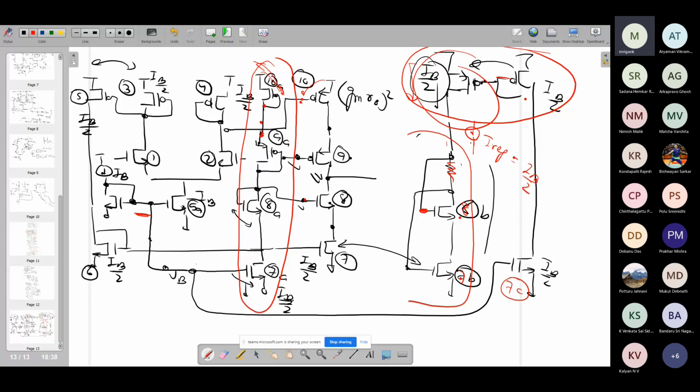This scheme will be advantageous because it will provide us higher swing at the output. If you remember the cascode current mirror with reduced swing, it helps us in getting higher swing at the output. The other scheme will also work. It will also provide appropriate DC values required for the gate of M8 and M9. But the swing available at the output will be smaller because it is the simple cascode, because you are having a VGS drop for M10, and also a VGS drop for M9.